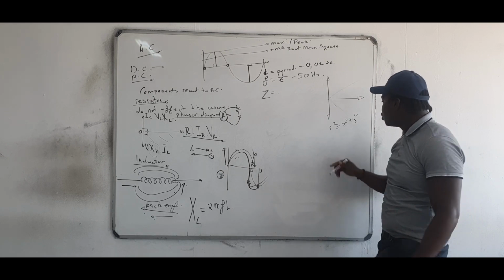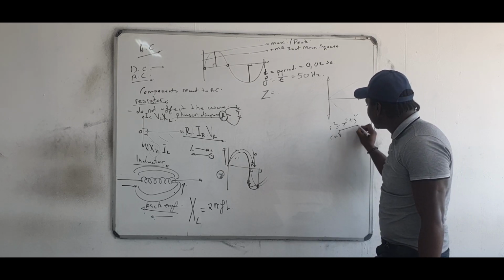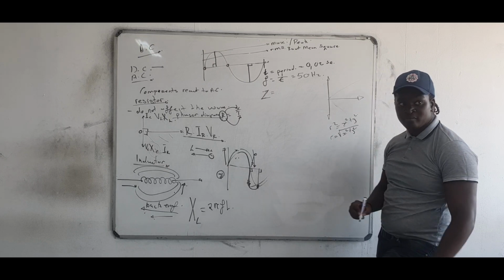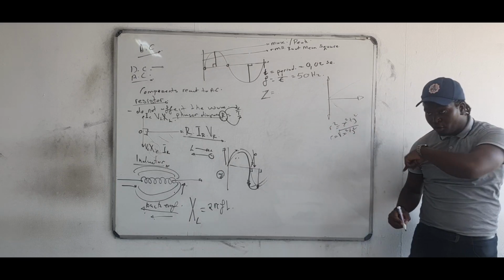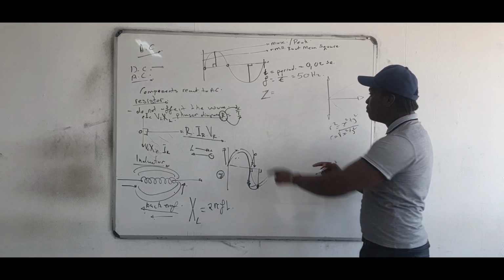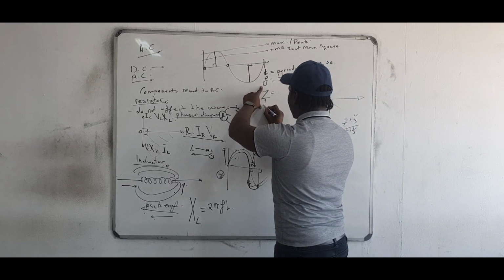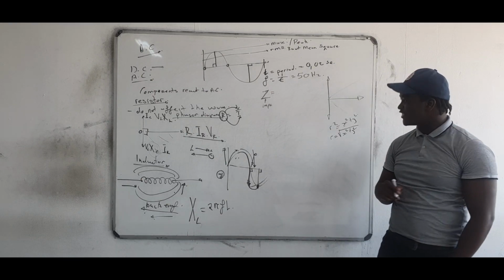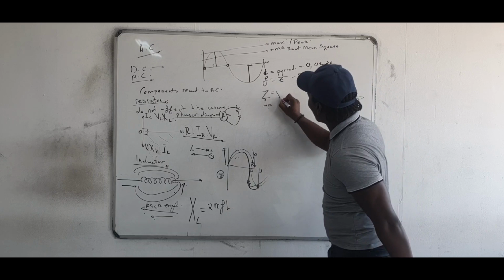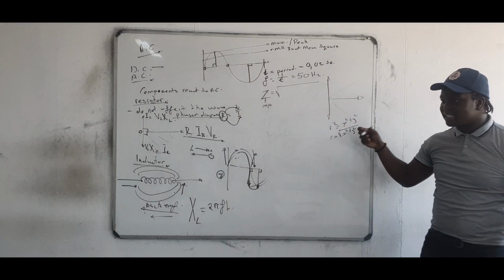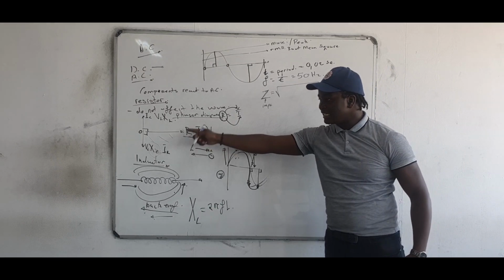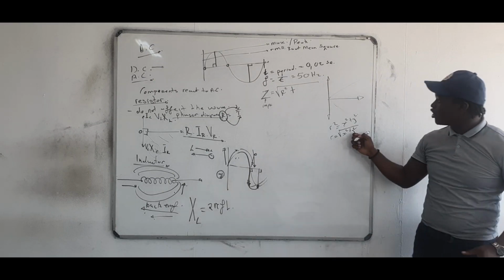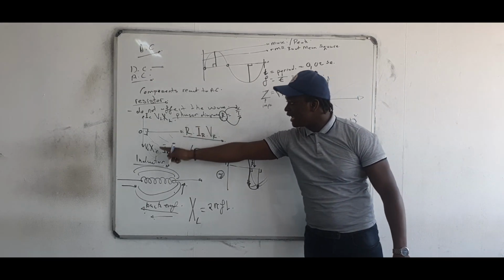Are we together? If you're going to do the mathematics, you can say, okay, I only want to look at r. You remove the square, you put the square root, you're now left with something along these lines. Are we together, right? Now, let's take this mathematical formula and apply it here. So that means Z, which is our impedance, is our equivalent total resistance. That is correct. Now, our formula is going to go like this. What is on our x-axis? It is our resistance. Are we together? So it's going to be resistance squared plus, what is on our y-axis? It's XL and XC. Are we together?